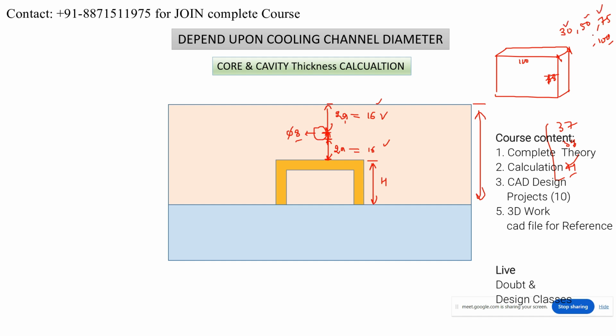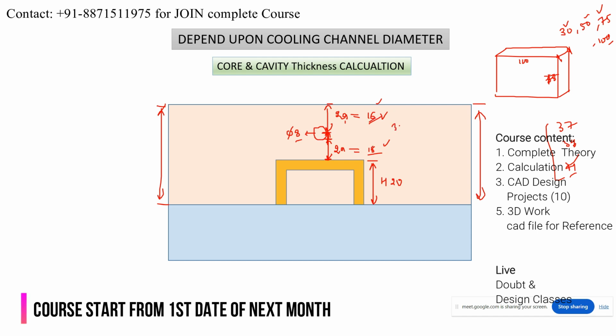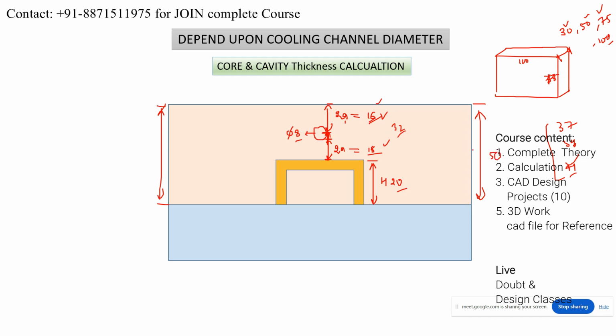Okay, so basically why I am telling you this point, because we want to save on manufacturing also. We don't want extra work, right? If we already have a thickness in the raw material, why would we go for machining? So for example, if the component height is about 20 mm, and this will be 16, so what should we take? Tell me. This will be 32 plus 20, so basically I will take 50 mm here. I will not take 52, right? Understood? Got it? This is a very important thing.